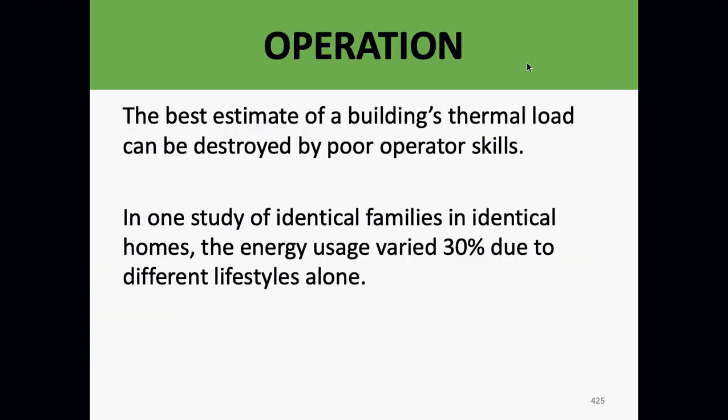The best estimate of a building's thermal load can be totally destroyed by poor operator skills. This means if you don't ask questions, if you don't understand the process, and if you just rush through these things once you get in the field, you can really mess up a building load. Small things like putting in a BTU versus a U value can really mess up a load.